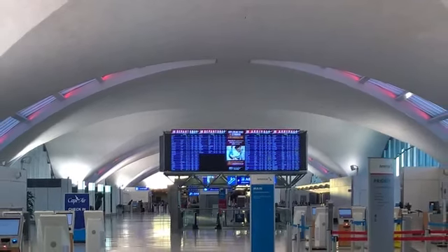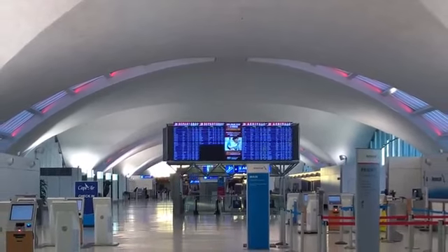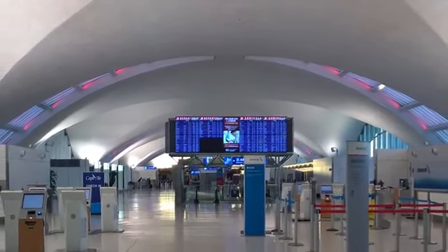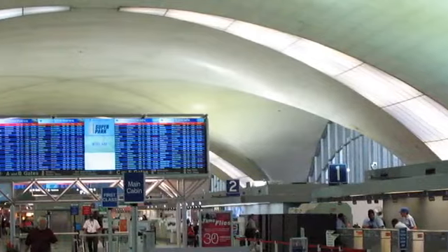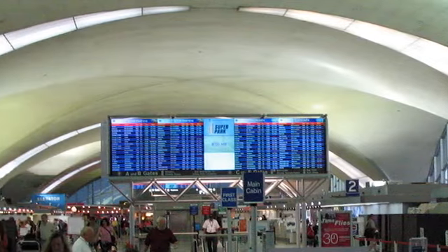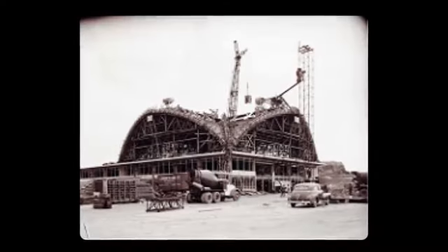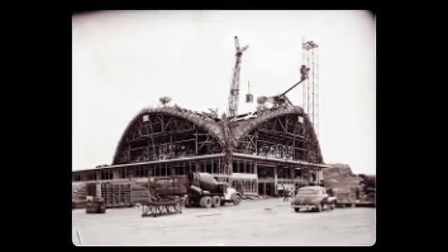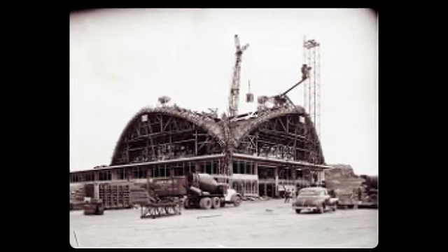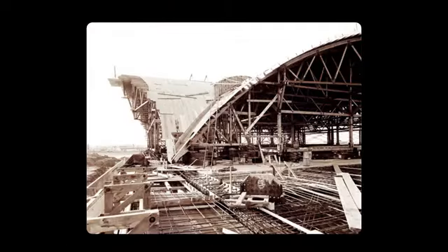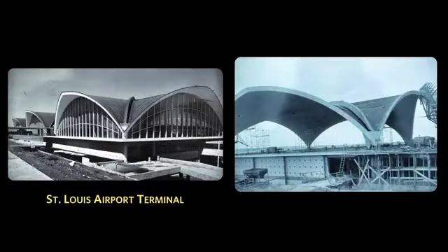This form of intersecting barrels is not the best form for a vault. And to the architect's dismay, Tedesko concluded that the vault needed ribs at the valleys and at the edges. This was essentially the wrong form for the vaulted design because it needed ribs. Visually, the ribs aren't so bad, but they conceal the thinness of the vault and make it look heavier than it actually is. I believe it would have looked more elegant without the ribs.